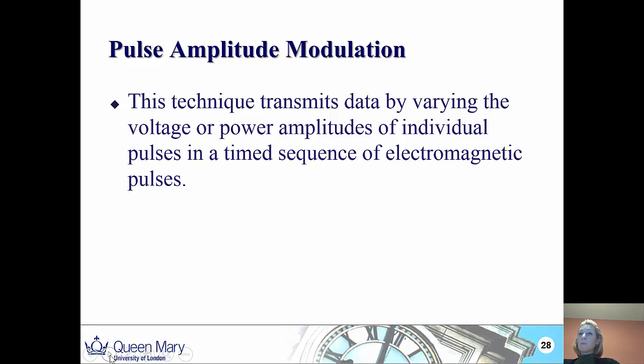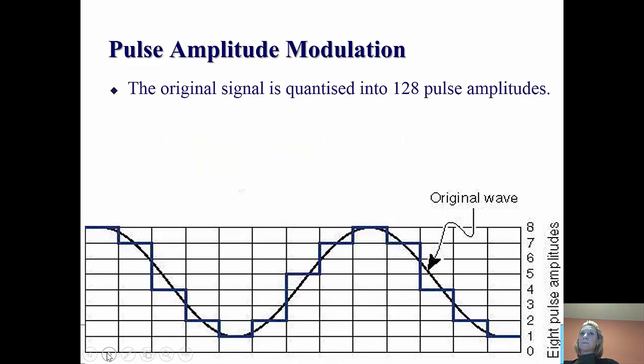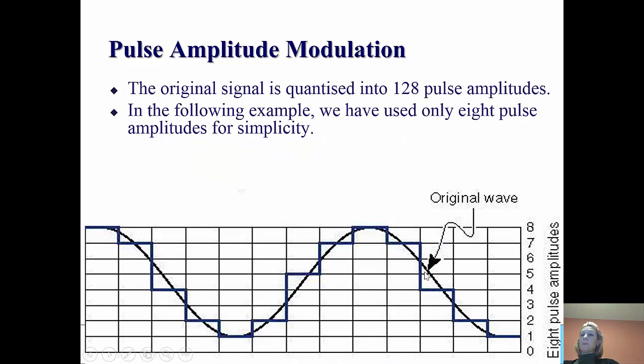Where we wish to communicate a binary 1, for example, we're modulating this frequency in order to represent this information that's being communicated. Similarly, when we're conveying a binary 0, we're not modulating this signal. The frequency is not changing from the carrier wave, and in keeping that state the same, we're representing a binary 0 as being communicated.